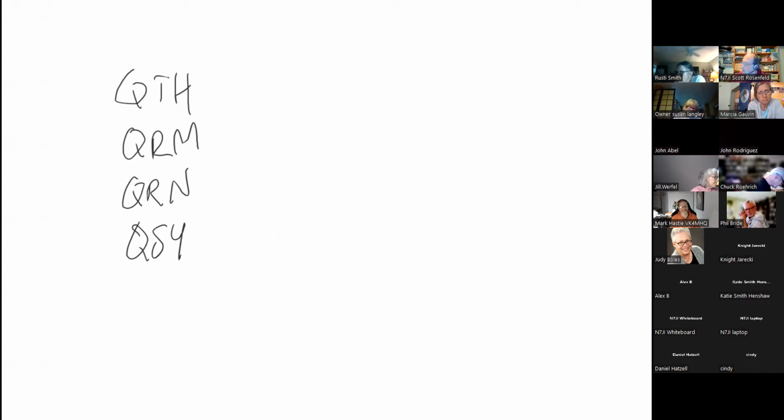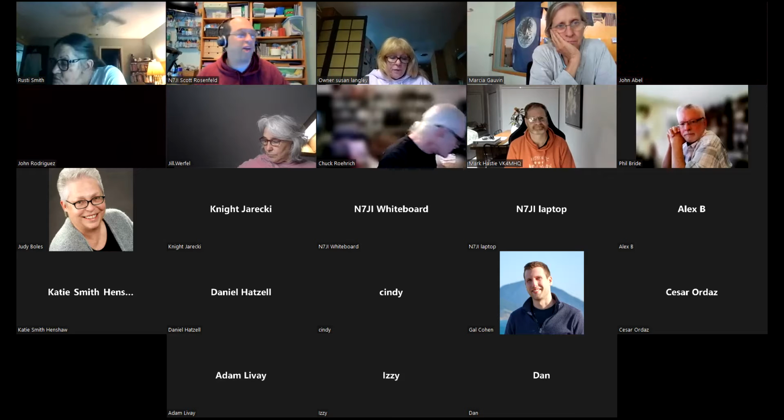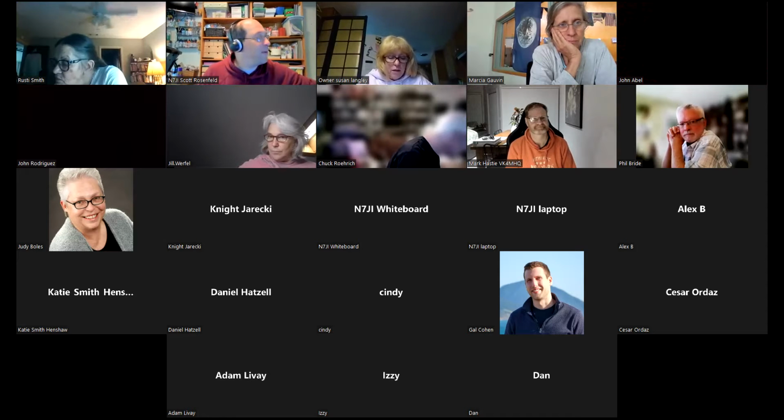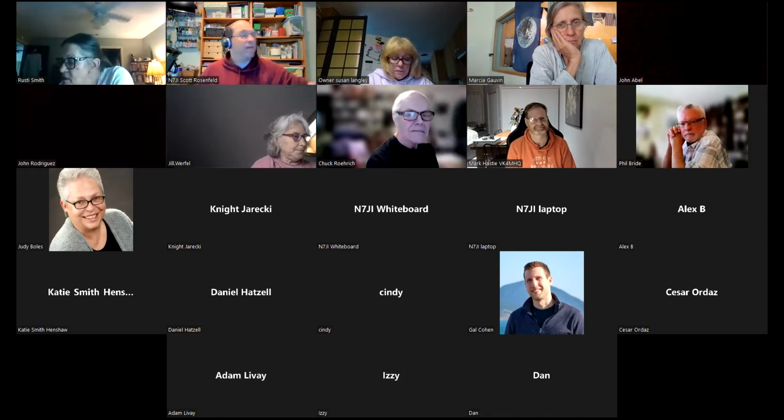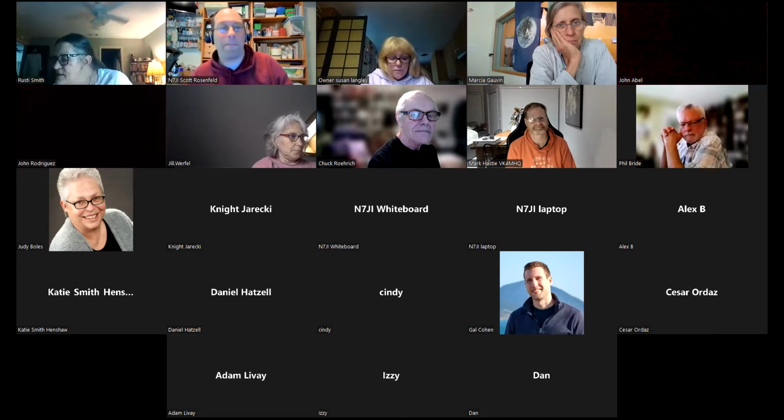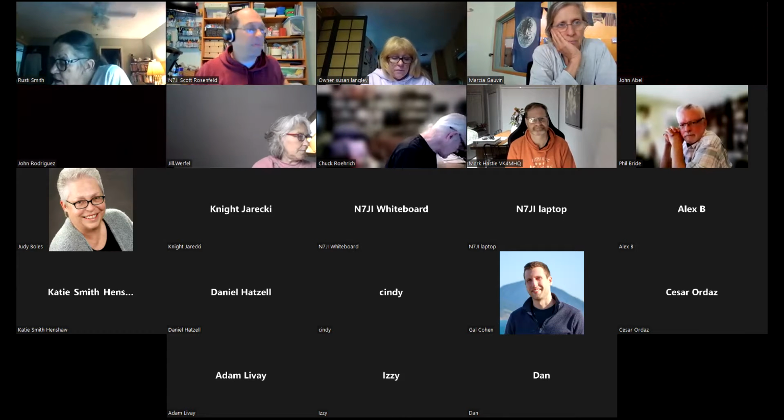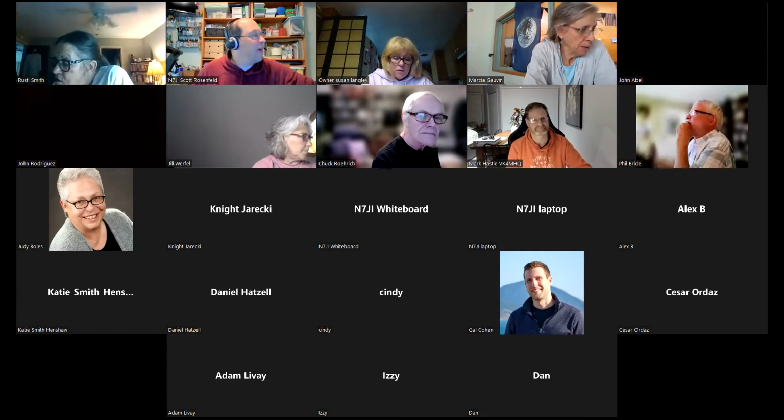Notice these are three letters because they came out of Morse code, which takes up a lot more than spelling something long out. So the ones that you need to remember are QRM and QSY. QRM means M for man-made noise. QSY means I'm going to change frequency. Or you can pose each of these as a question. QSY question mark. You want a QSY? Sure, let's QSY. It means the same thing, just as a question. QRM or QRN? The N is natural noise, so static crashes.